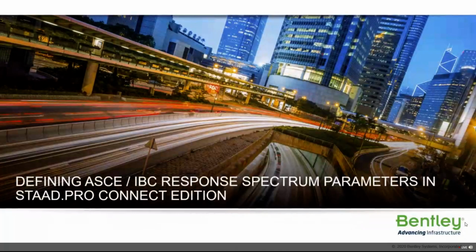We also need to remember that the mass and the stiffness modeling are a prerequisite for the response spectrum analysis, and which has been dealt with in detail in the last two sessions. So we will start off by discussing the torsion specification and the associated de-eccentricity and the eccentricity commands.